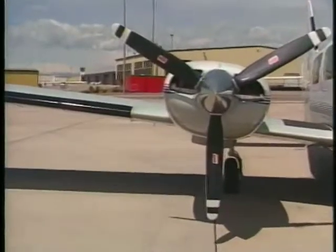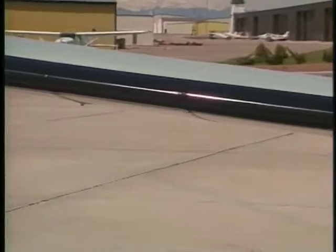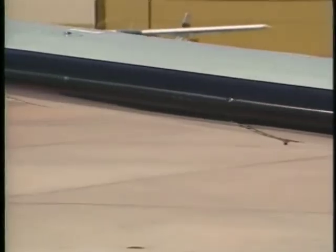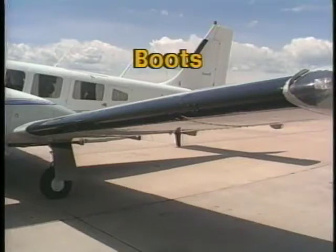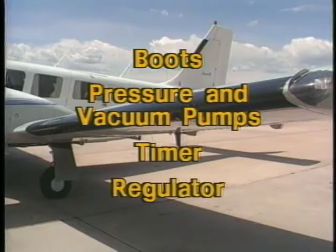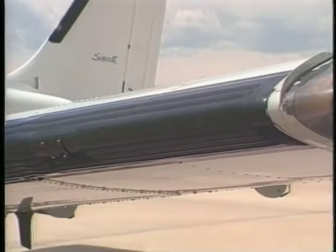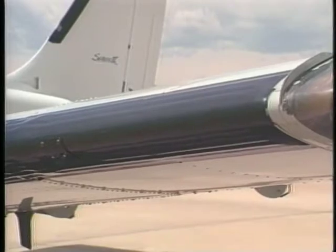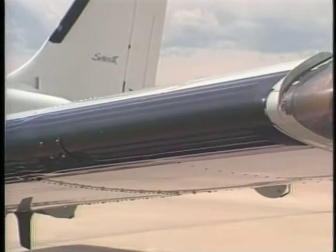Many piston-powered aircraft have pneumatic airframe de-icing systems on the leading edges of wings and tail surfaces. Normally, this system consists of inflatable boots, engine-driven pressure and vacuum pumps, a timer, and pneumatic regulators. The engine-driven pressure pump inflates the boots while the vacuum pump deflates the boots and supplies enough suction to keep the boots flat against the leading edge of the wing. The timer controls the inflation-deflation cycle.